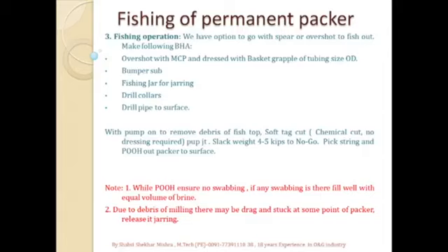If there are some deformities during the cutting inside the tubing or the pup joint, or the hole is not clear inside, or some fill is there inside, we go for the overshot for the fishing.